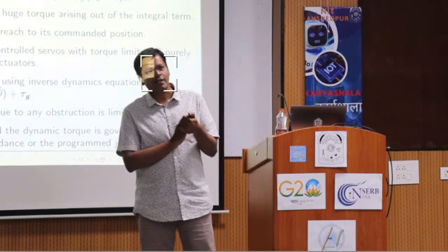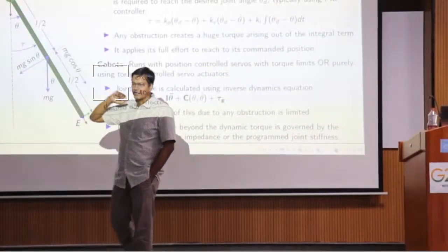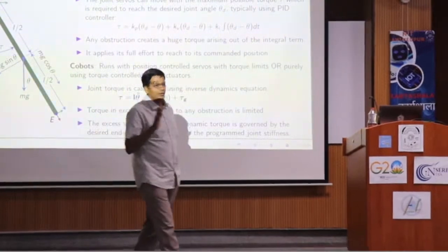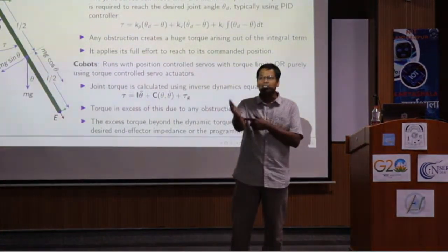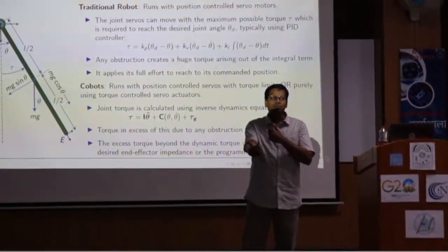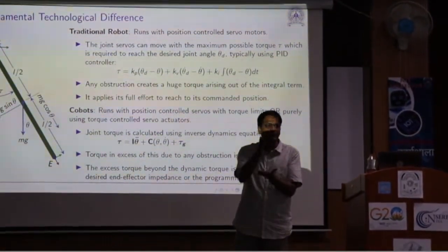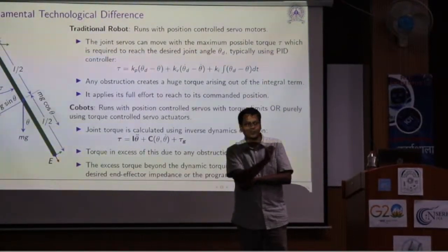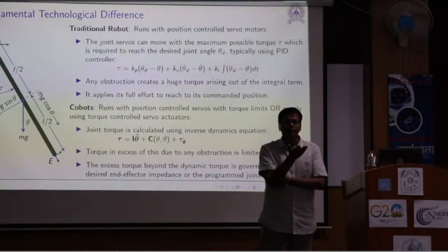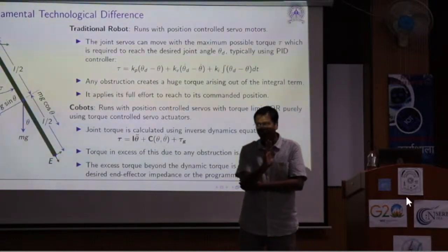Normally I was taking feedback from the joint, that is joint angle. I commanded my robot to go to a place based on the joint angle. I commanded for the angle, took the feedback of an angle, and then compared them. If at all it reaches there, you have to stop it. In order to do so, you have a type of controller. Can be a PID controller. Normally, industrial robots have that, so it is stopped there.